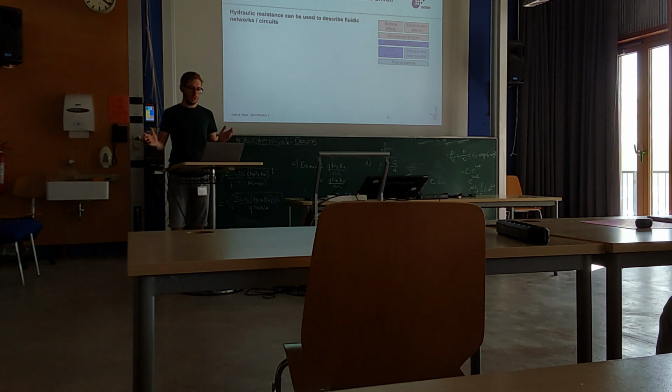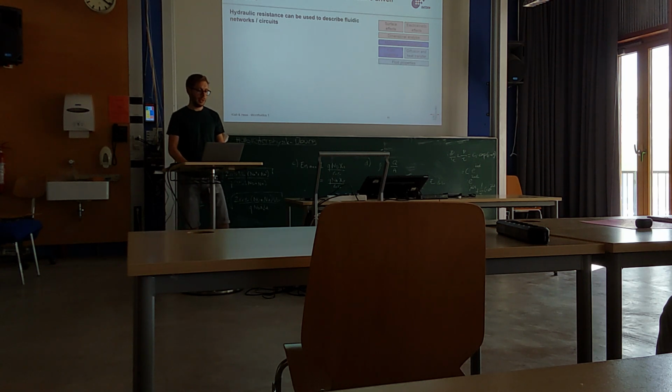So how can you now, let's say, lay out a pressure-driven chip? It's quite easy. We discussed this already. This is the network and fluidic analogy. If you have a lot of hydraulic resistances, meaning you have a lot of channels which are connected in a series, then you can just perform this simple addition to calculate the equivalent hydrodynamic resistance.